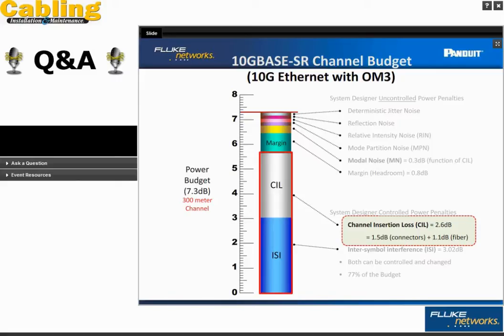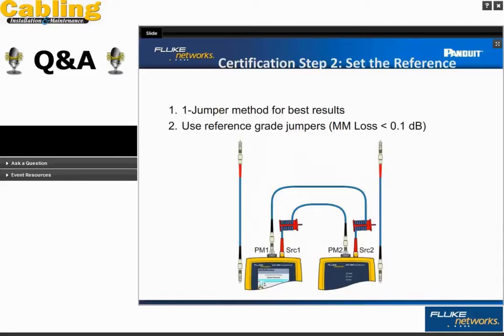So the purpose of using a mandrel when setting a reference is, I'll give the technical answer and then break it down. The purpose of using a mandrel is to remove what's called higher order modes of light that will disperse or absorb once a test is underway.